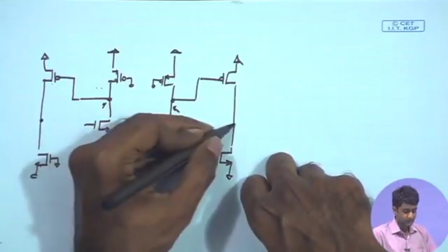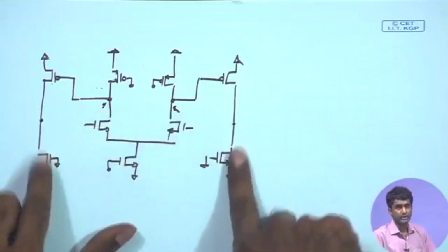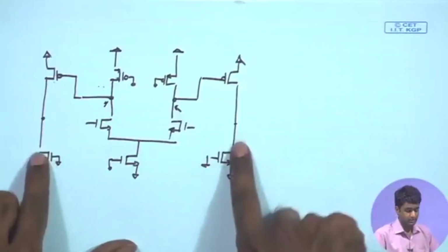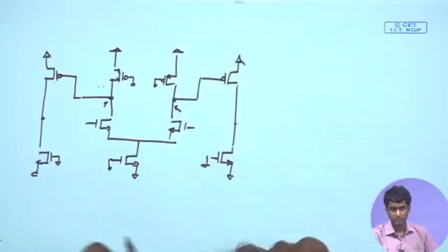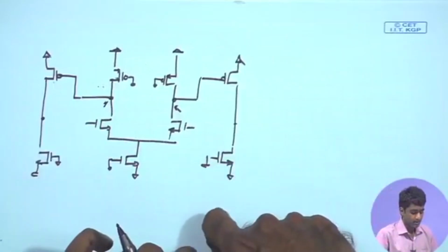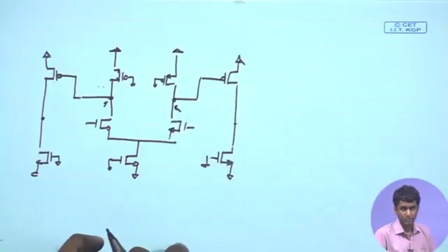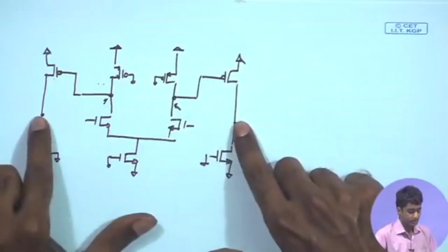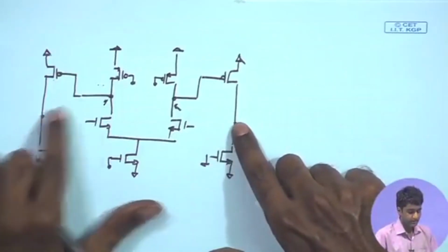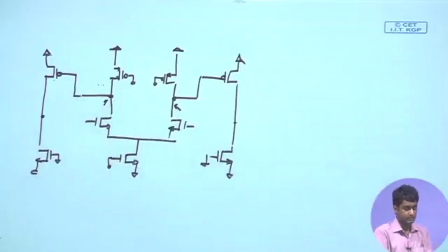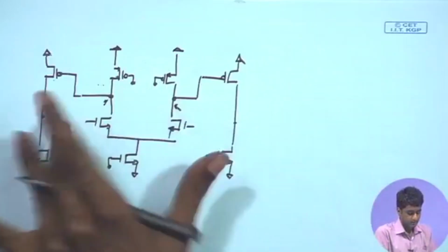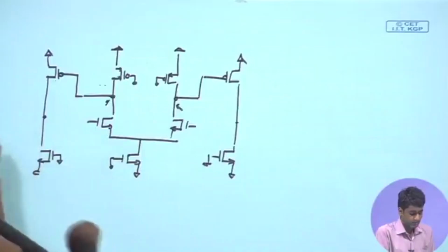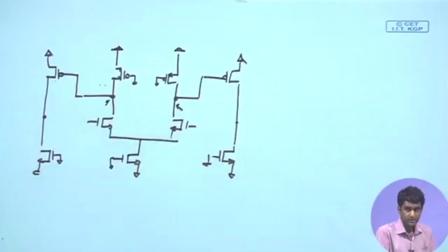Likewise, at the output point, anyway they are acting like common source amplifiers with current source load. As a result, the overall impedance over here is also going to be RO by 2, and we can find out the overall capacitances connected at this point. So, we can look at the overall parasitic capacitances coming at these 2 points, and that is going to give me the final parasitic RC value, and hence from there we can calculate the overall poles for this transistor level circuit.